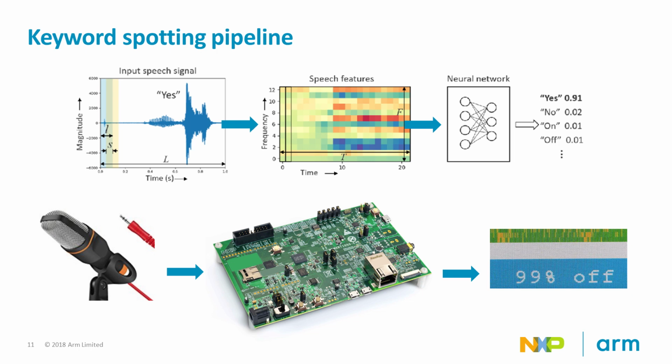An acoustic signal is recorded using a microphone connected to the audio jack on the i.MX RT evaluation board. The codec provides a stream of digital audio data converted to floating point values at the input stage to utilize the Cortex-M7 floating point unit in the audio pre-processing.